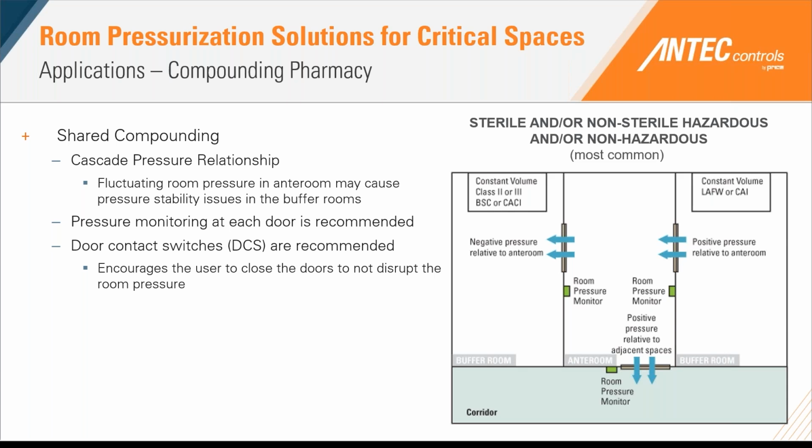Now, we strongly recommend in compounding pharmacy applications to utilize pressure monitoring at each doorway, so that we can properly isolate and monitor that key pressure relationship for that space. Additionally, door contact switches are strongly recommended, so that if a door is left open, we can alarm and encourage users to keep those doors closed in order to not disrupt the room pressurization in this pharmacy.